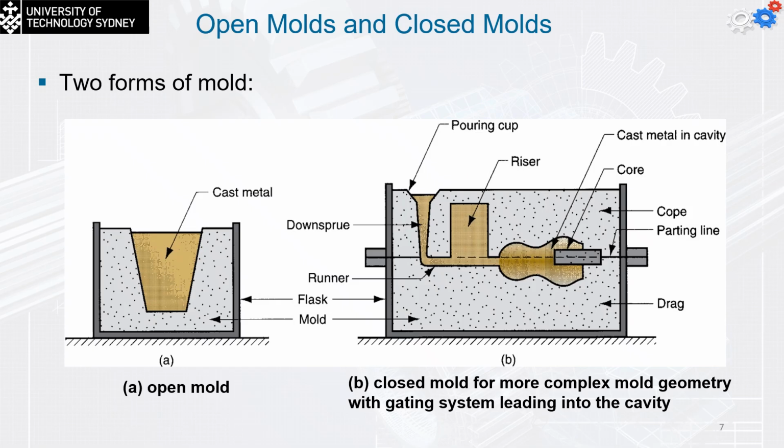And the other type, which is the closed mold, the cavity is going to be inside the mold. Only the pouring cup and the vent actually is going to be open to the space, to the outside. The shape of the mold, the closed one, is going to be a very high possible question in the quiz.